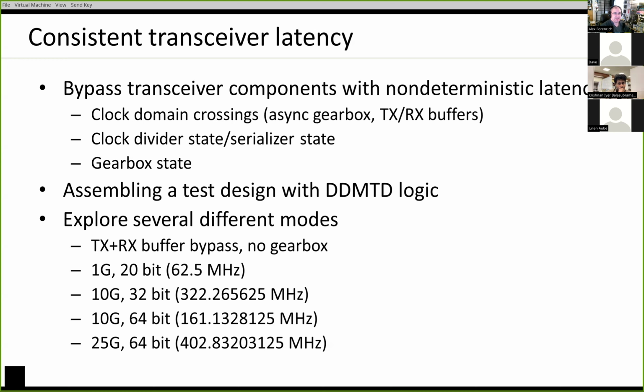So I'm not sure exactly what problems they're running into there. I'm sort of trying to repeat that work as well, and also come up with a way to do this for other devices, right? It seems like every FPGA family is probably going to have to do similar characterization to figure out how to configure the transceivers. I've heard that they've had to play some weird tricks to make things work. And I guess part of it is that, while you can reset transceivers multiple times until you get the latency you want, you also have to have a way of characterizing that, and a way of knowing when you've actually hit the value that you want.